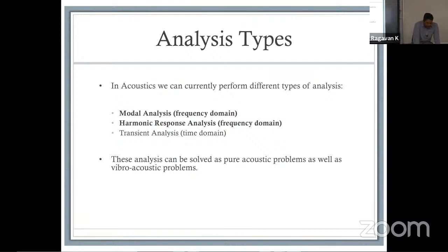When you're talking about the idea of a coupled acoustic model, something to take into consideration, like I said before, is that they're both interrelated, which means a change in your frequencies can lead to a change in vibration, which can lead to a change in the acoustics you hear, right? So this is essentially a coupled problem. Once again, if you define acoustics solely on what you're measuring from your unit, you might not be solving the problem. Because if you only want to solve the problem of acoustic noise, you can put a jacket around it.